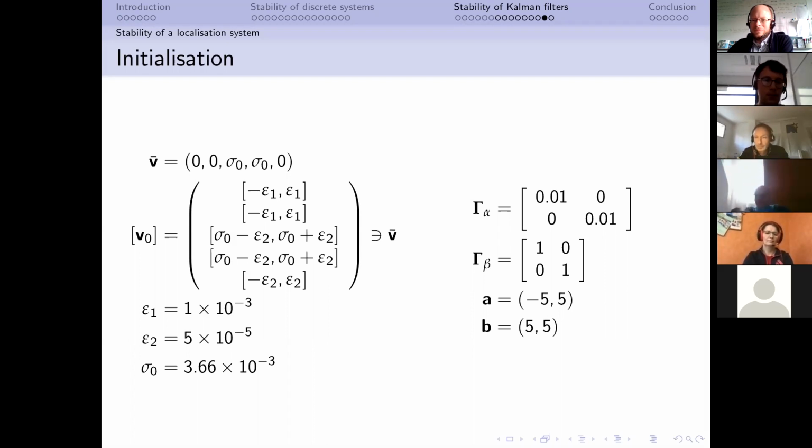You can really do whatever you want. The point here is just to transform your system, which is just a Kalman filter algorithm. But if you have a robot that runs continuously in time, and you have a computer that makes your Kalman filter run at a given frequency and a controller at another frequency, then what you can do is take the smallest frequency of them all, discretize your whole hybrid system, and then you obtain a discrete system with a given frequency, and you can just study this discrete system and prove its stability with all the parameters you've been choosing before.